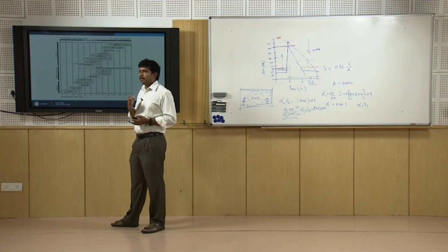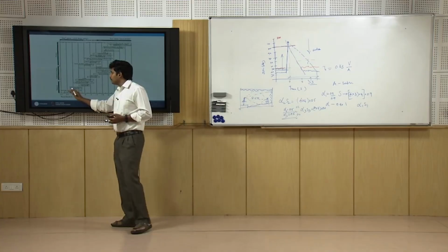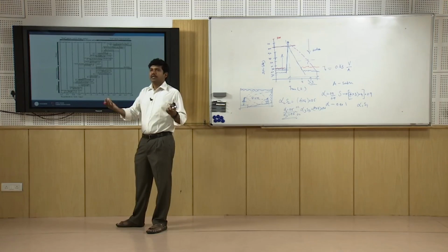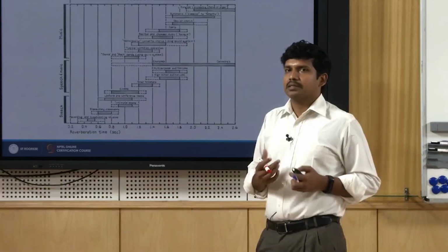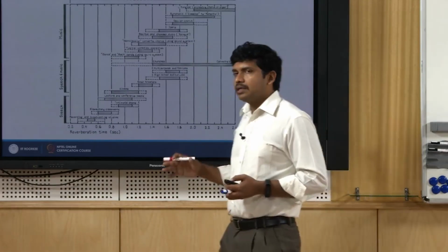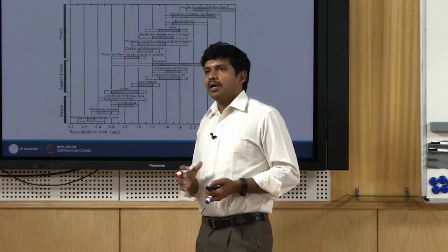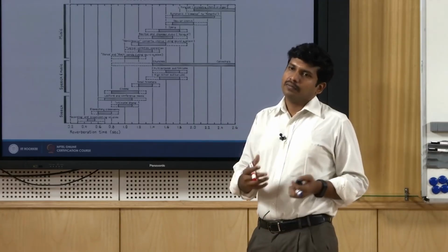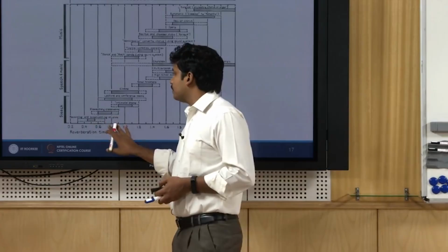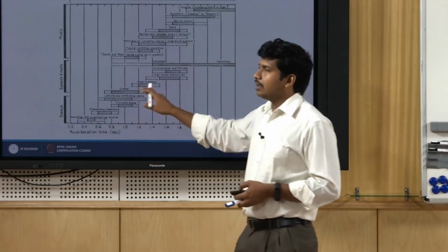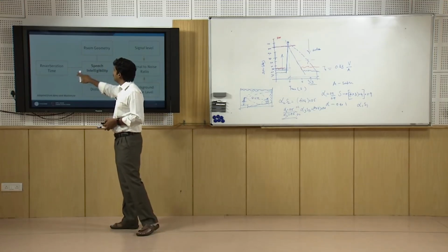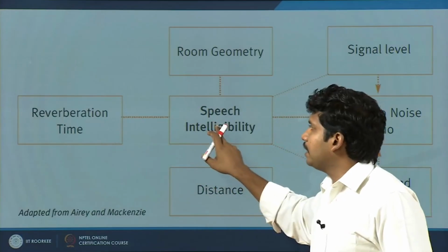The syllables have to have a continuity when you especially have music performances. Even for speech, in order to reinforce the original sound, the signal versus the reinforced reflected sound, initial reflections we call, or early reflection, you need a certain amount of reverberation in order to avoid difficulty in speaking for the speaker and for an appreciation of listening on the listener's side. So a certain amount of reverberation time is needed, not too high, not too low. It depends on various factors. Speech intelligibility is primarily affected by reverberation time.